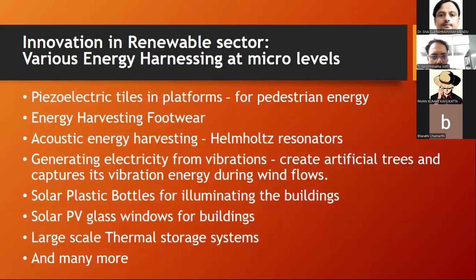Milliwatt to watts. And as I told you already, there are some footwears used as energy harvesters while walking, jogging or trekking, or for army purposes. Army people use this energy harvesting to activate some sensors. Similarly, there are acoustic energy harvesting devices like Helmholtz resonators, which oscillate a piezoelectric strip and generate power in the microwatt range.